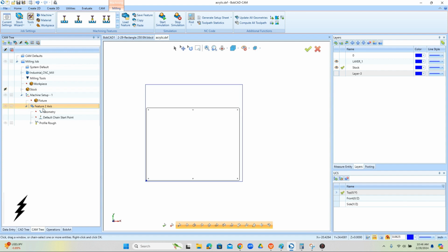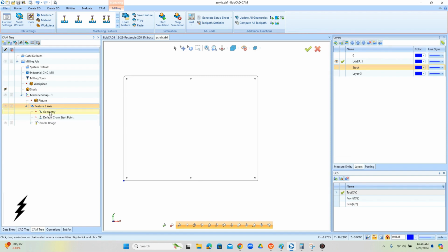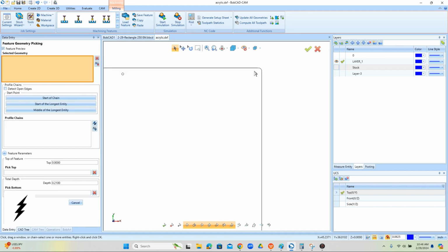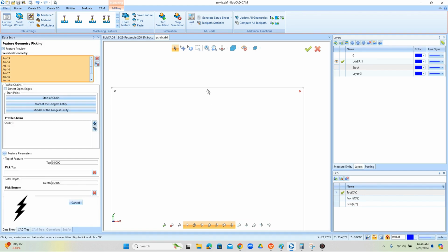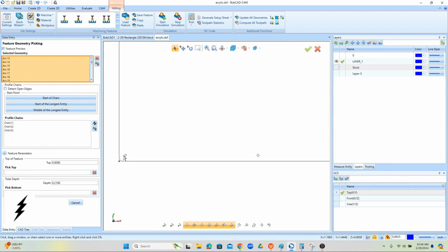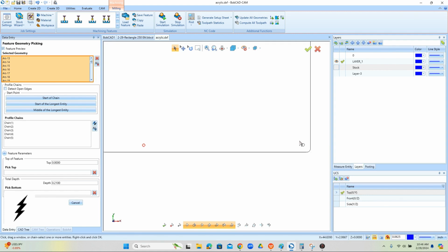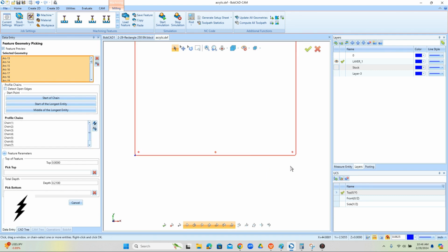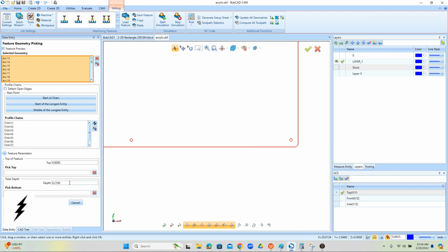And then over here, this is our profile cut. So let's turn off the other geometry. And we want to come in and select this. So we're going to do right click, reselect. And we'll come in and select in the order we want it to cut in. Now, sometimes it doesn't matter. You can just let it cut in any order. Other times, you like to control which way it's going. Sometimes when you do this, you forget to offset to the correct size and you make mistakes. So, you got to slow down and pay attention to what you're doing.